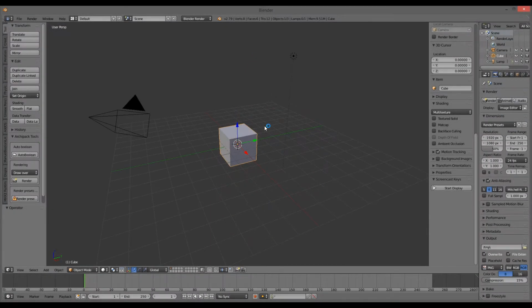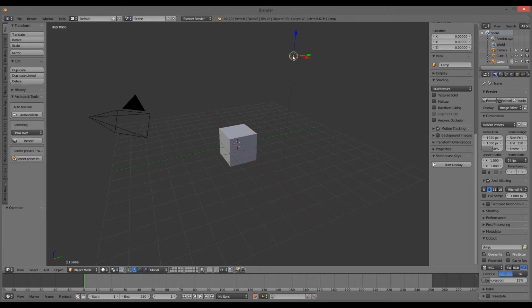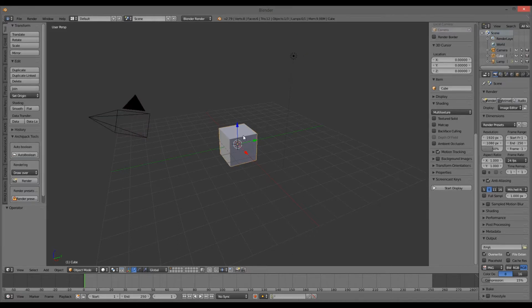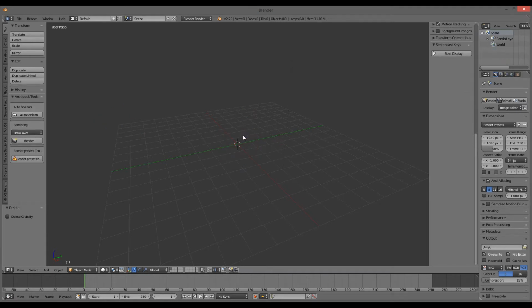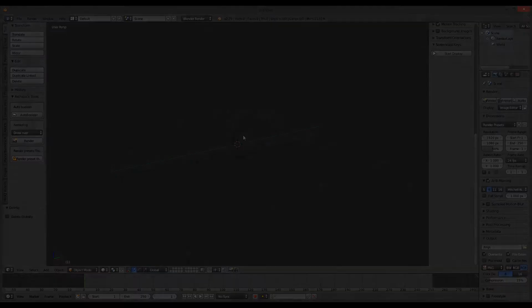Now let's start Blender. You will see Blender's default scene with a cube, camera and light source. Object selection in Blender is done with the right mouse button. To select all visible objects, just press A on the keyboard. To unselect all, press A again. So select all objects by pressing A and delete them, pressing Delete or X followed by Enter to complete the operation. Now let's import our models with expressions.